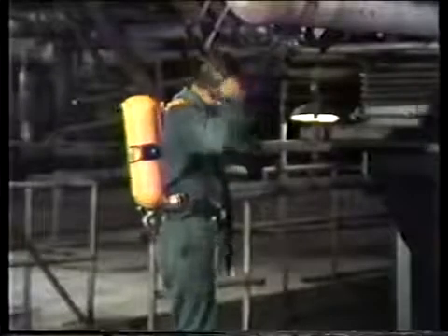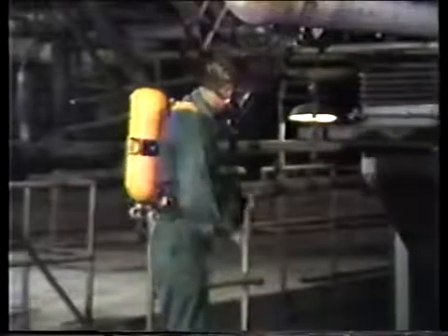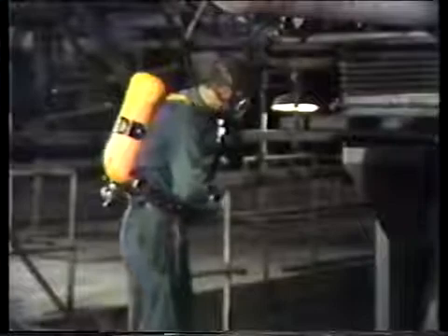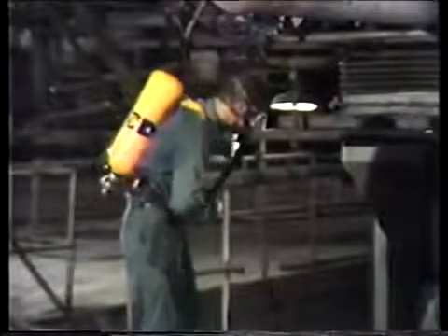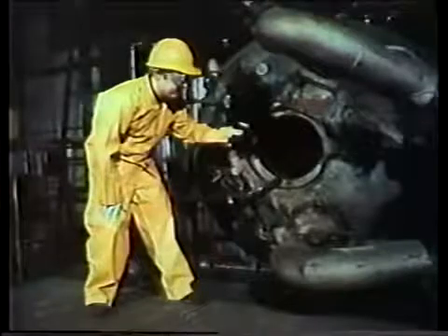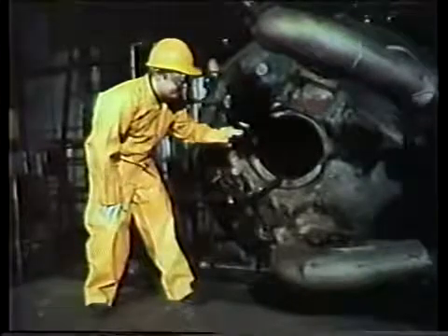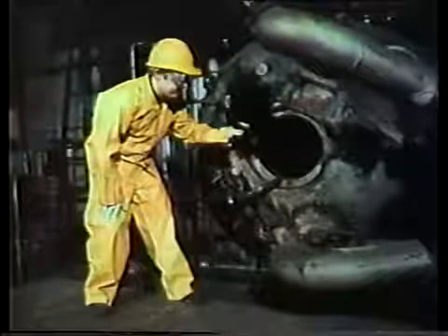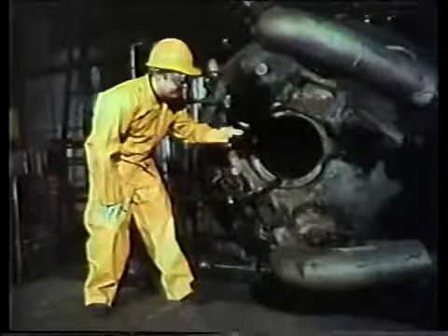A self-contained breathing apparatus like a Scott Air Pack is used where ammonia vapor or other fumes are too strong to be removed by a filter. Strong fumes could be found inside boiler areas with bad ventilation. Protective outer clothing should be worn anywhere there's a chance of being splashed by the chemical solution. A rain suit and gloves will protect your skin and work clothes from coming in contact with the chemical.